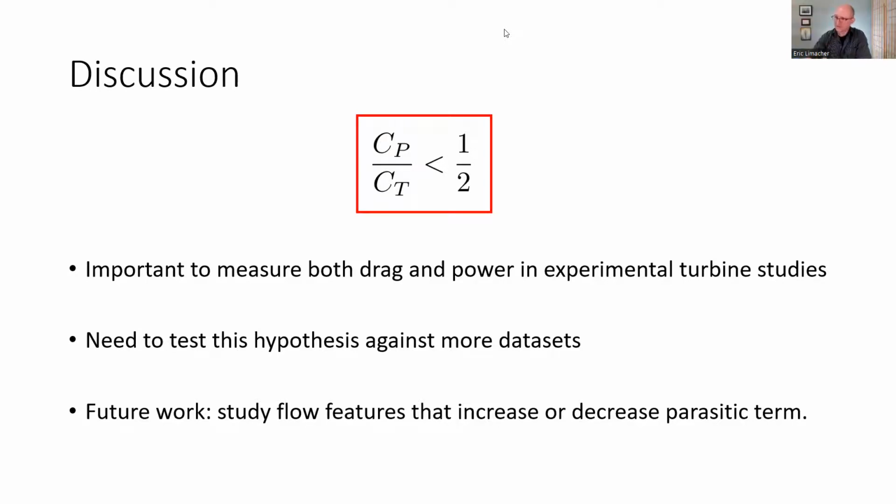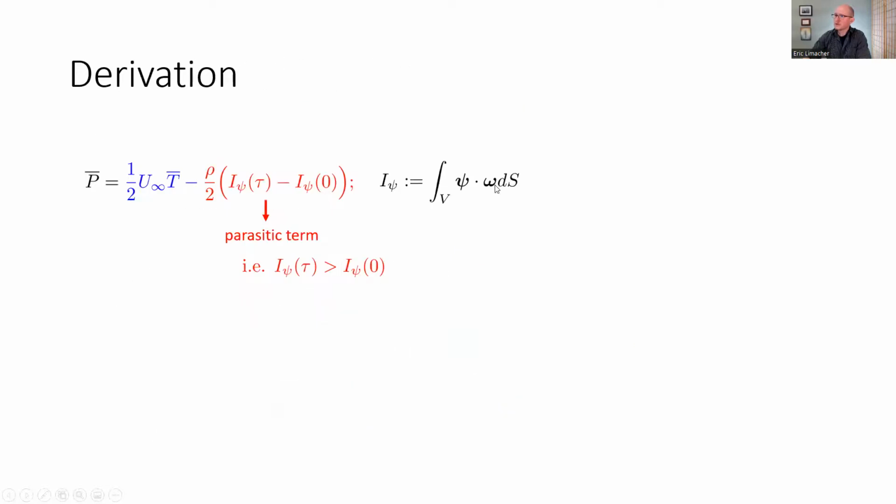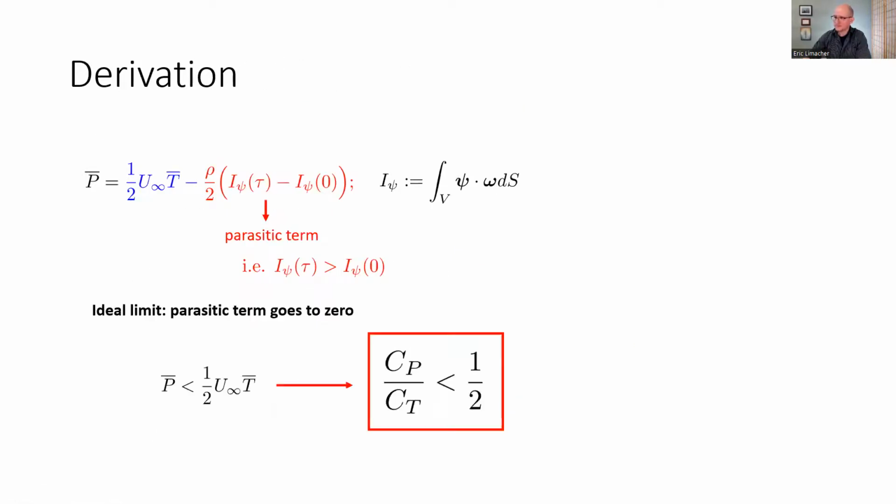Yeah, so I'll just go back to this expression here. So the viscous effects are, it's interesting you bring up that point, because even in the kinetic energy balance that I've shown here and that we use in a typical derivation of the Betz-Joukowsky limit as well, we are actually neglecting the possibility of energy being transferred to the thermal energy balance, right?